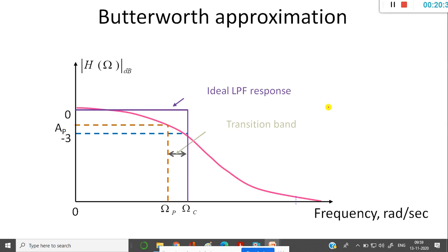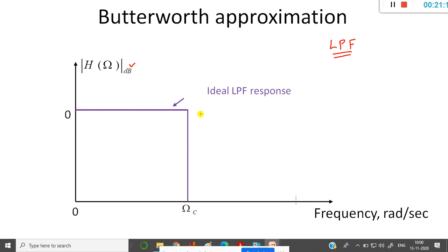This is the Butterworth approximation method. When I want to design a low pass filter, which is nothing but in the frequency domain, what type of graph do I use? A semi-log graph, because everything we analyze is in terms of decibels. Now, this is a practical ideal filter.